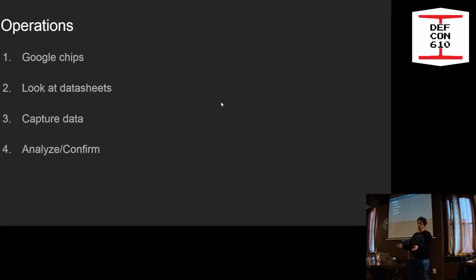Then you capture the data that's going to the chip, and you basically confirm that the data going to the chip is the correct data, and you can get magic packets often that set up the device that you don't have access to yourself, but you can then use that data yourself, just replay it, to use it in your own product. You often find weird things that they do that are not in the datasheet.